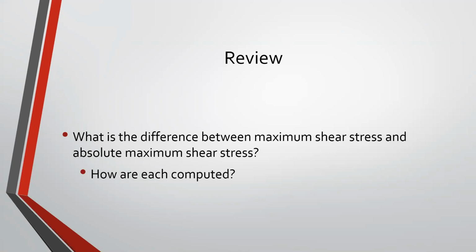All right, so what he's trying to say is that when we rotate an element in a particular plane and we look at the different stress components that happen on that face as we rotate it, there was an equation for R that pertained to that circle that we created, and that was our maximum shear stress in that plane of rotation.